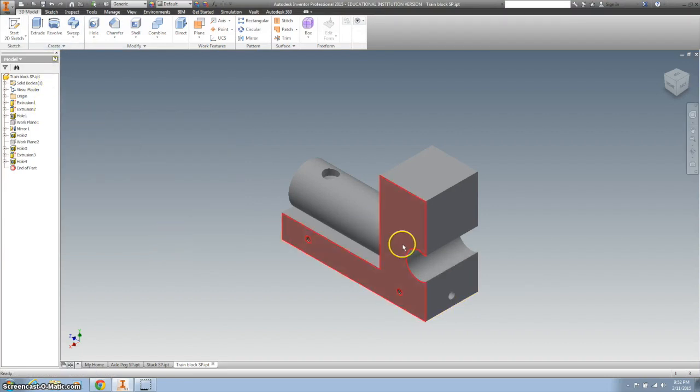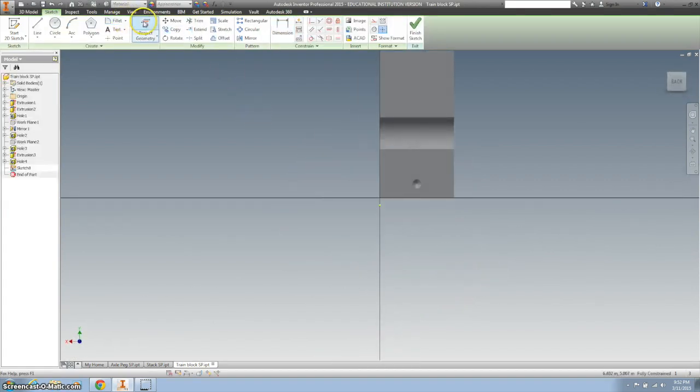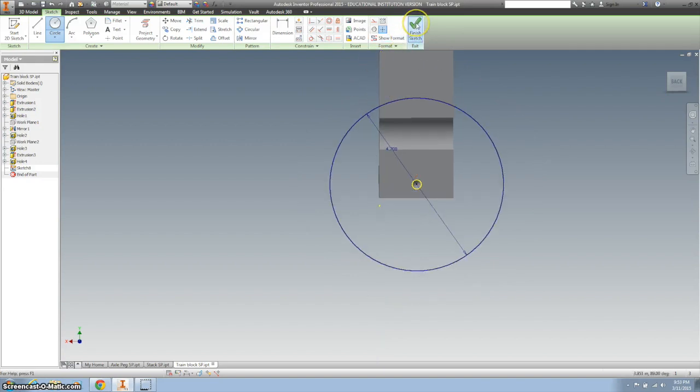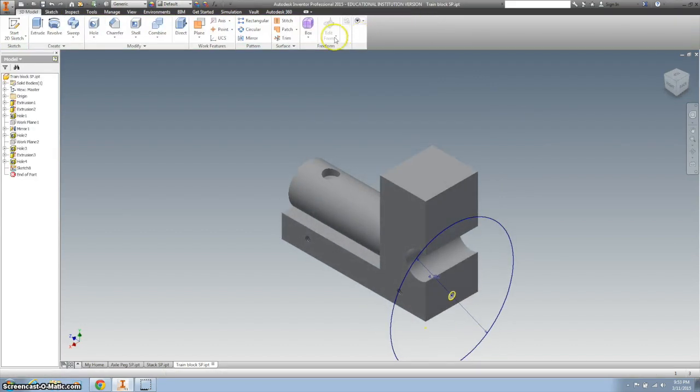And now we're going to finish up the top. So just one more thing. Alright, so start a new sketch. I'm going to project this circle here because I want to make a circle that is centered on that. And we want that to be with the radius of 2.35. Since it's a radius, in my case, I have to times it by 2 because mine's solving the diameter. Let's go ahead and finish that.